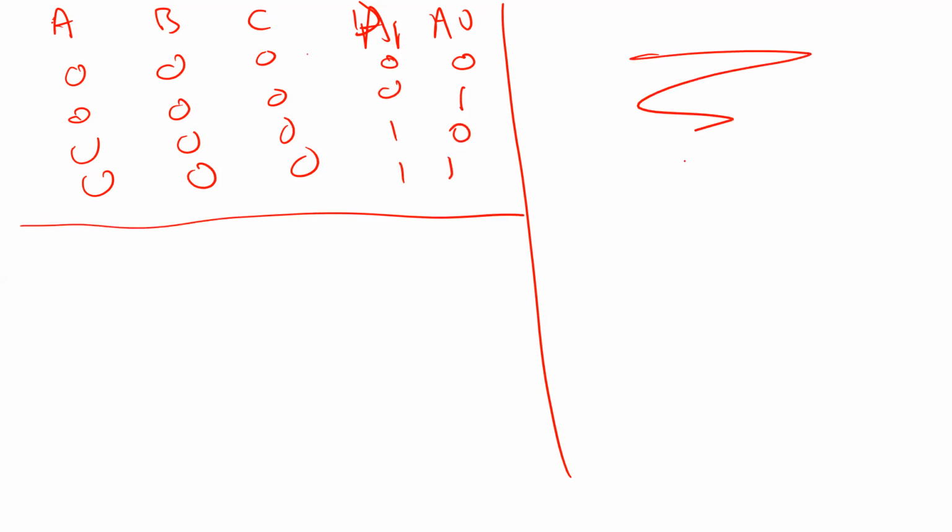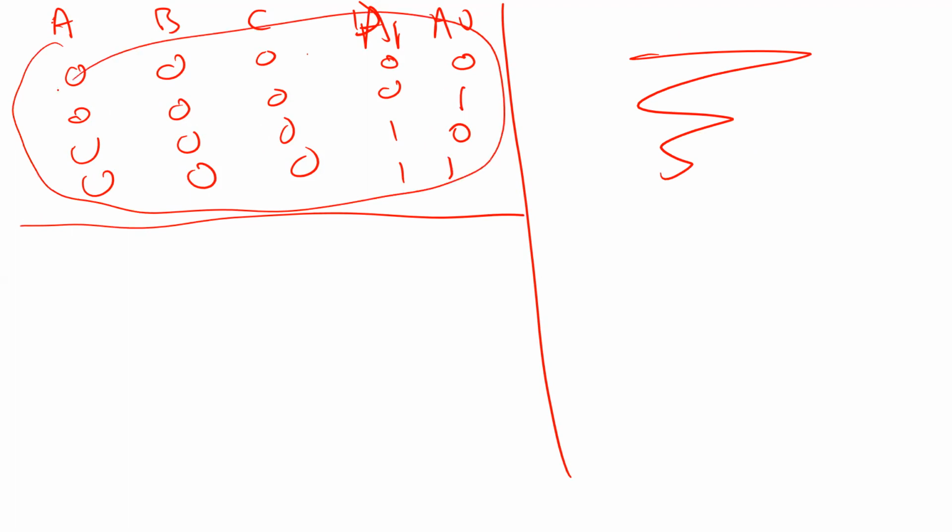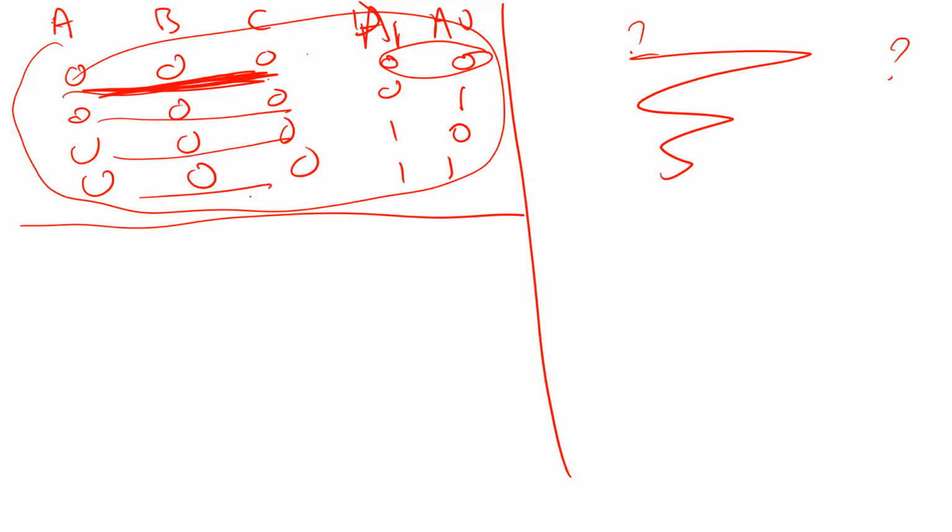And then to fill up this part, for every state, if you are in state 0 and this is the input, what should be the next state and what should be the output? You can easily get this information from the table. Same thing for this one. You have to go all the way until you reach state number 4, which is actually 1, 1, 0, 0.